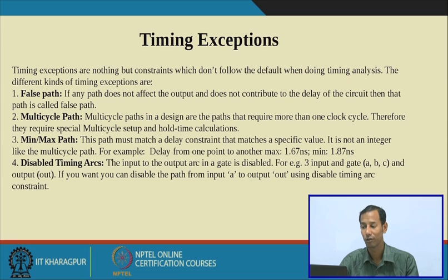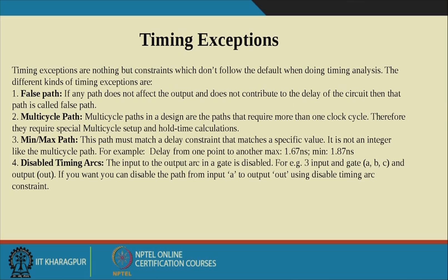Then there are disable timing arcs. Suppose for a gate I have three inputs, A, B and C, and the output is out. Now I want to stop input A from affecting the output.